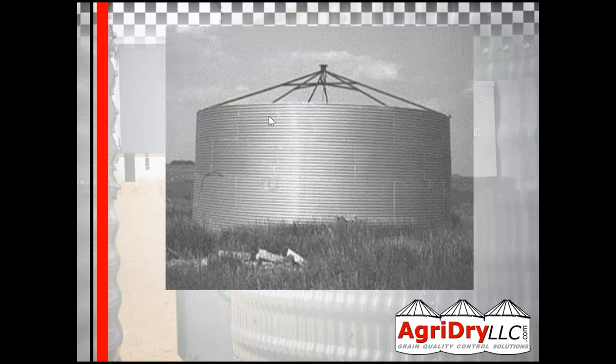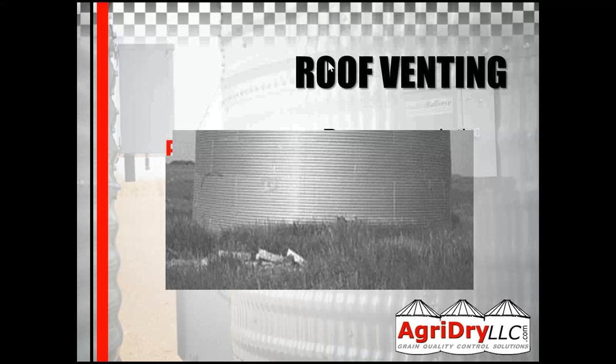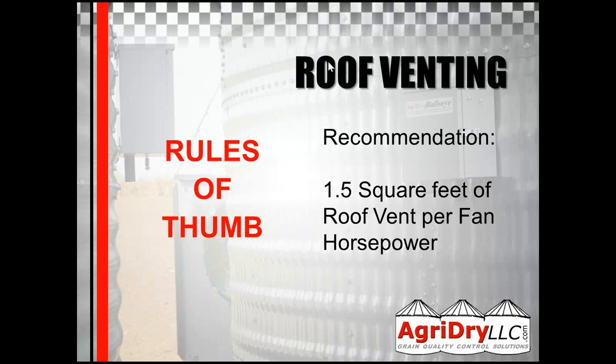This is not efficient, obviously, to have an open top grain bin, but to represent what we want to do with roof vents is try to simulate the best way to have an open top bin. Have those roof vents spaced out all the way around the bin from the peak to the eave, and simulate so if you had no roof on it, that airflow would be consistent all the way across the bin from the center to the outside. That's what we want to represent. Obviously, we can't have a grain bin without a roof, but we can simulate that idea with roof vents when we place them on.